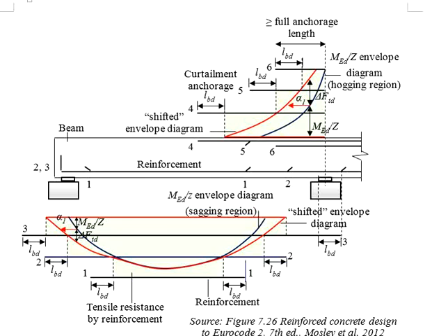Due to different magnitudes of the loading, as well as different types of the loading, the bending moment diagram may differ, which later you will need to convert from the bending moment diagram into the tensile force diagram, and then you need to work out the amount of reinforcement bar provided, check the resistance provided by the reinforcement, make sure it is always greater than the shifted tensile force envelope.